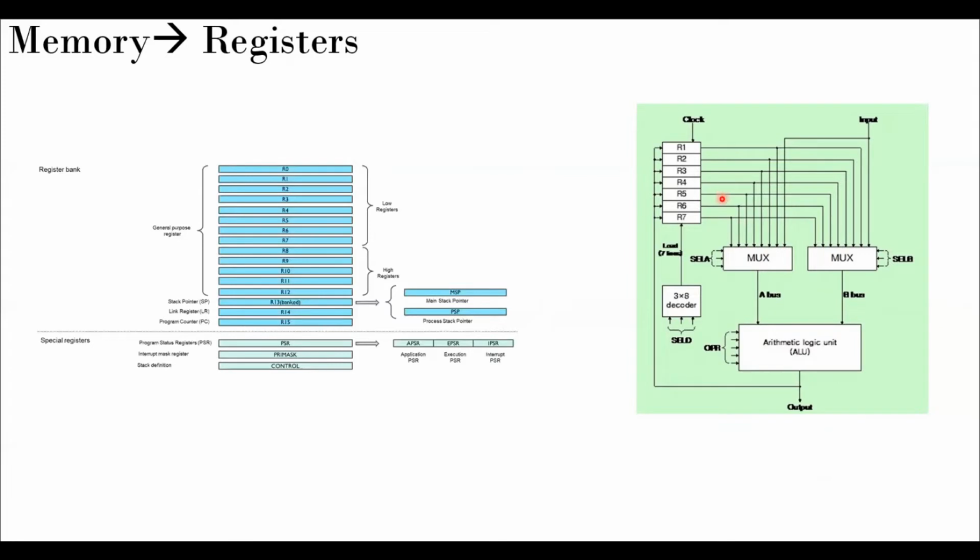So you can think of individual, there is a hardware digital circuit inside, which connects the registers individually to the ALU through some mux arrangement, something like this, a multiplexer arrangement like this. So this is important to have in your mind. They are very few in number. You just cannot add registers on and on, because then that increases the complexity of your core. You can't afford that, right? So very few registers in number. And modern day machines typically have around 12 to 13 general purpose registers inside the core. That is even high-end machines I'm talking about. Okay, so that is a general trend.